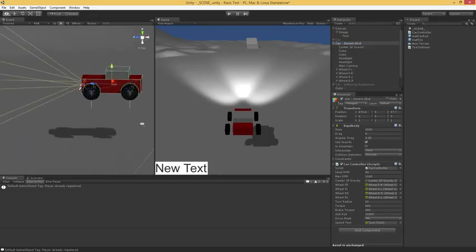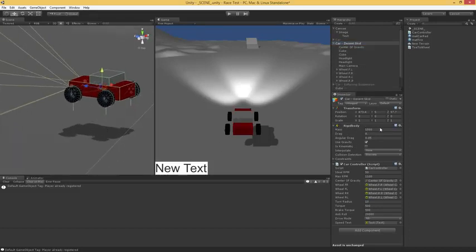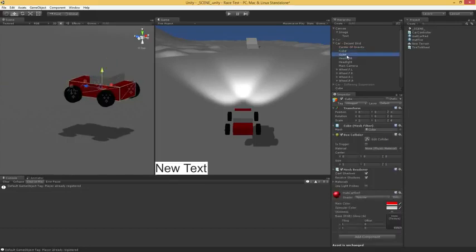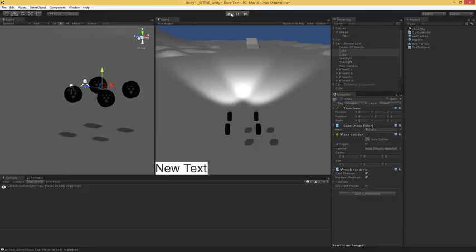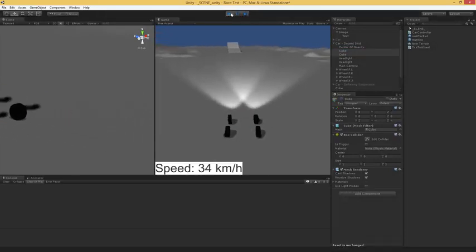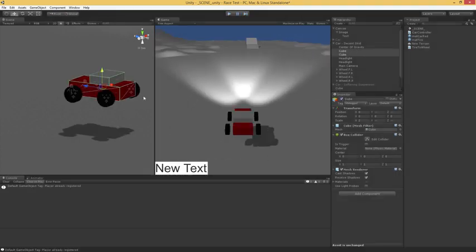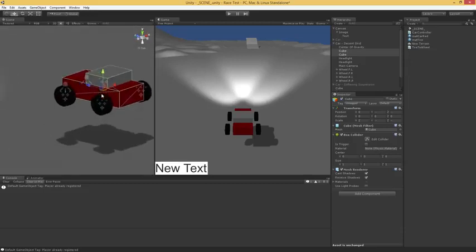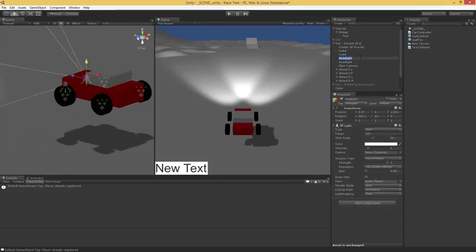So if we look at the object itself, it simply has a rigid body and the car controller script, which is what's going to be included in this package. Inside of that, first of all, it's got these 2 cubes that simulate the body. Now, it should be noted, these don't really have to exist. If I disable these, I'll still get the tires, and it's still working. The big deal is if there was a pole, we'd now be able to go directly through the pole. We wouldn't actually hit anything there. So if you go into your modeling software and model a proper car graphic, you're going to want to replace these 2 cubes and drop in your actual mesh of your proper car in there. I've got a couple of headlights turned on just for visual effects.